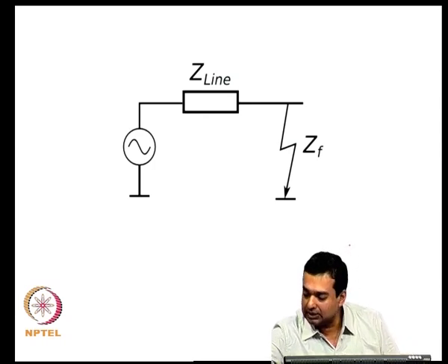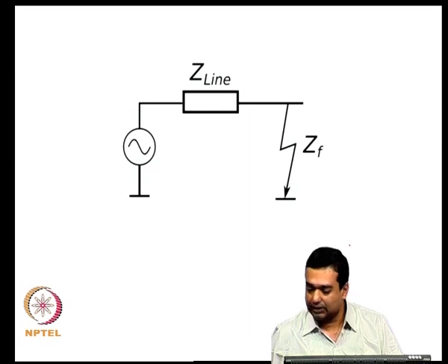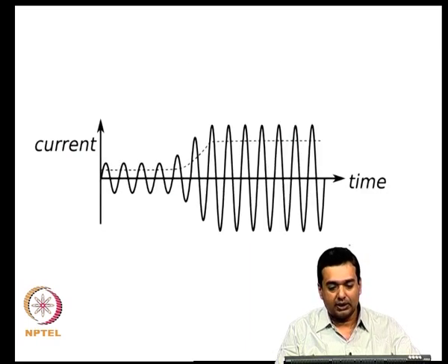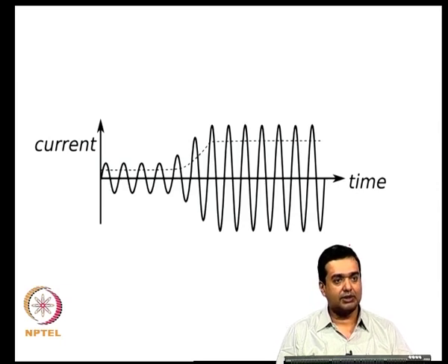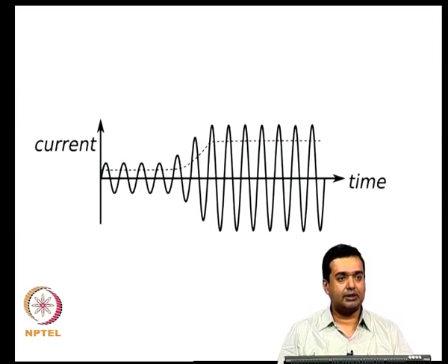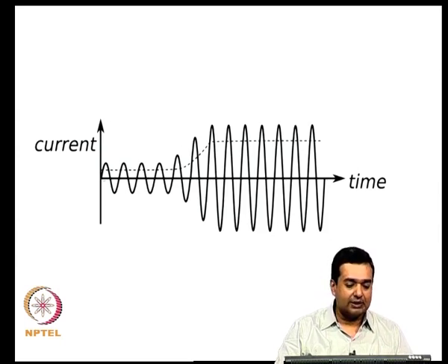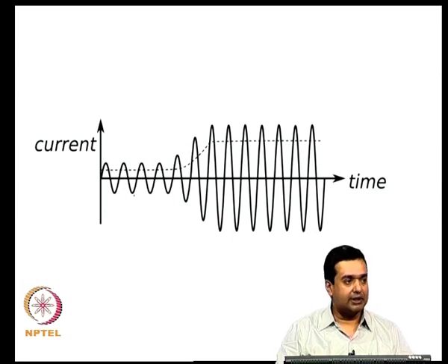One thing to consider when you are looking at the fault current models in power systems and traditional distribution system protection application, when you are talking about current levels and voltage levels, you are talking about things in the RMS time frame. If you look at the instantaneous currents, they might be going in a sinusoidal manner.